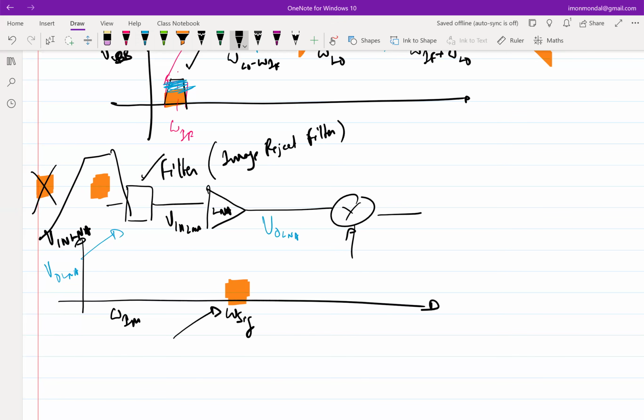Make sense? Now, if I say the output of the LNA adds noise, right? So the signal noise is there, plus the LNA is going to add its own noise. Might be less, might be more, depending upon what noise figure you have. But if it's more than a 3 dB noise figure, then it is adding a significant amount of noise, right? So it might be slightly less than whatever you had at signal, but you are going to have some noise load, in a different color, right?